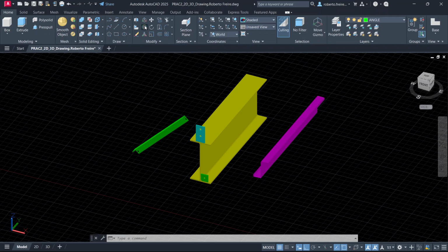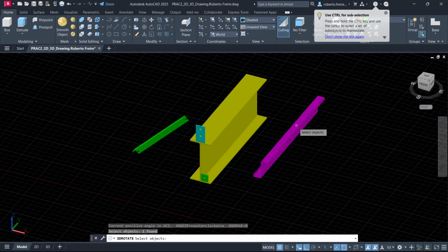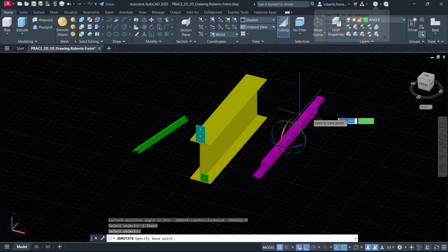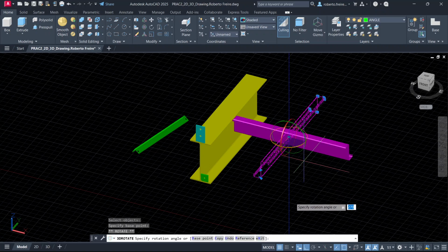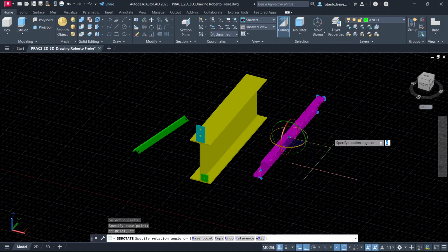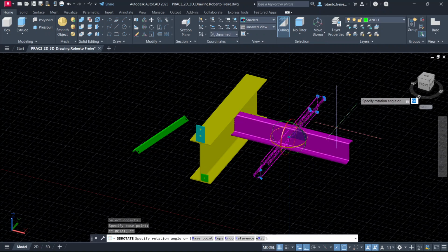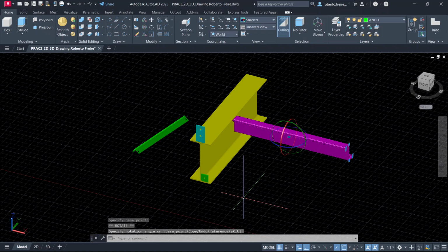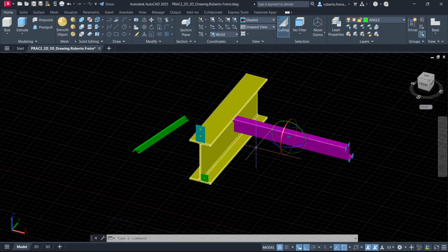3D rotate, again, that command. Select your object, press enter, and now they have to rotate in a blue color. Select the blue one, and then make sure to move your mouse to the front, not to the back, because this is the opposite way. So I need to move my mouse down, to the front of this where you can see my information, and click there. And I've already positioned this one 90 degrees with my rafter.